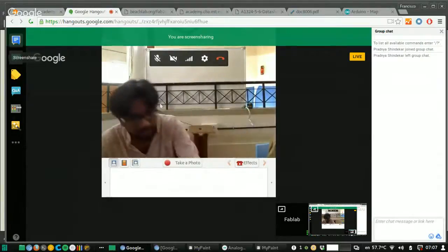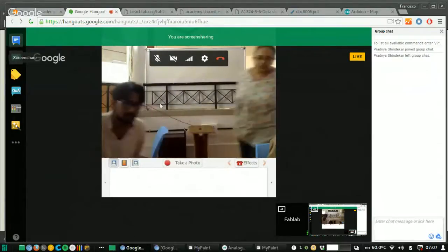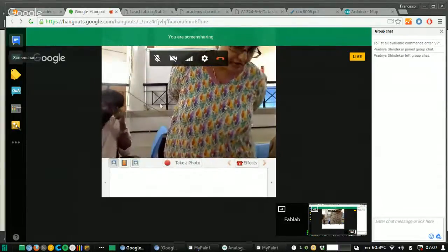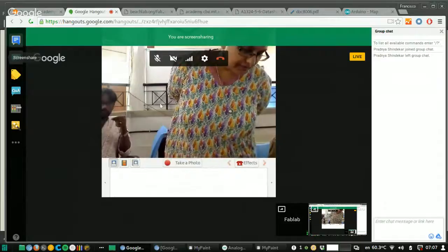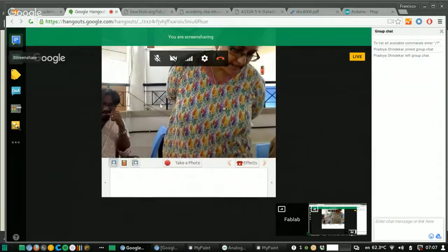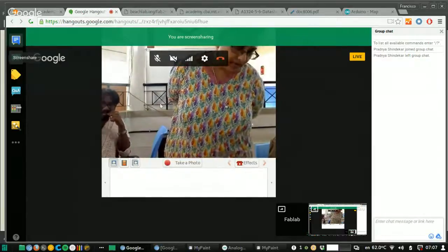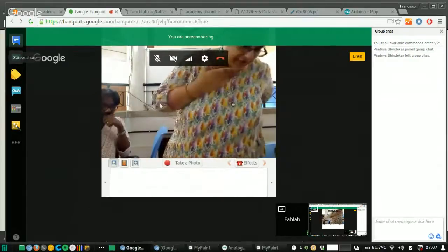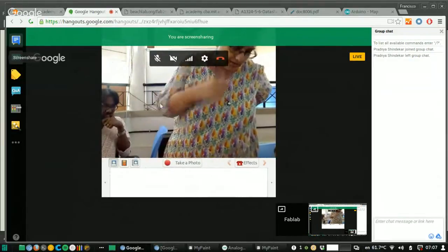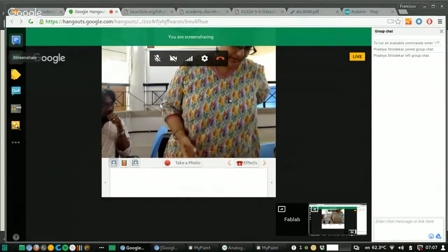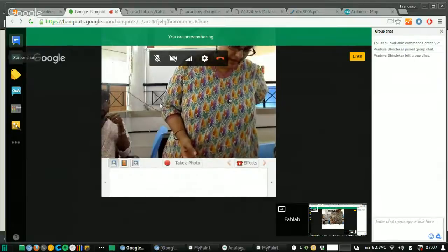I've managed to test a button. I managed to do the first exercise that you had asked us for, the debouncing with the oscilloscope. So I tested a through-hole component because the board wasn't programmed. I first simulated bouncing, and then I looked at debouncing. And I'm still trying to figure out what analog input to test.